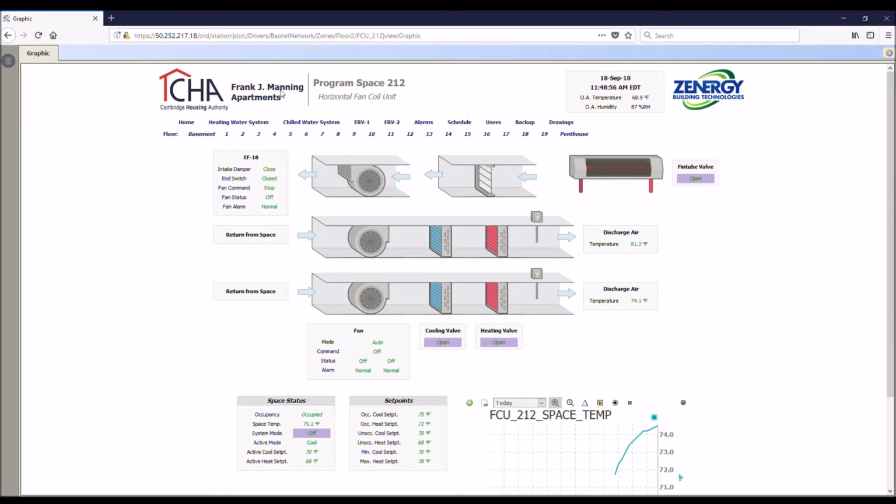The exhaust fan here, we're not monitoring the space pressure in this space. It's just always circulating air out of the space, so I guess we kind of want a negative pressure in this space because the fan is always exhausting and there is an intake damper, so if it gets too negative in the space, naturally we'll pull air through the intake damper as we're exhausting.